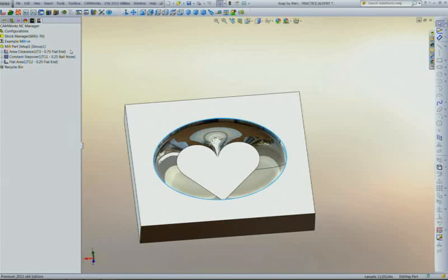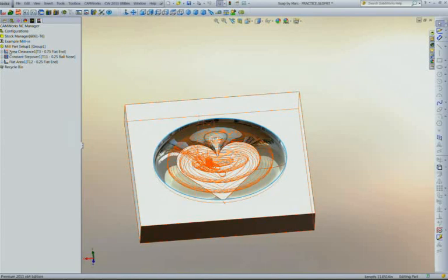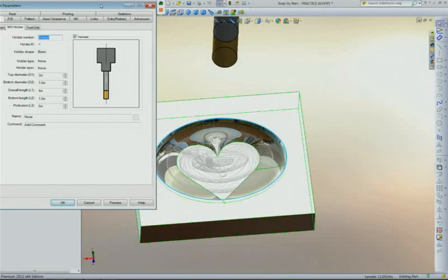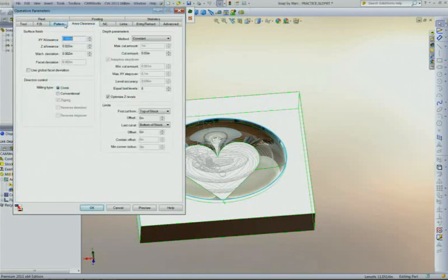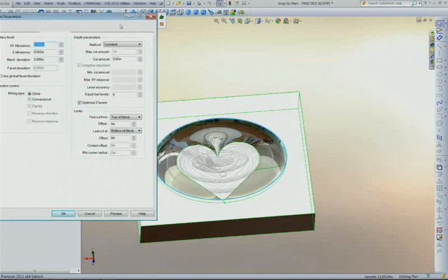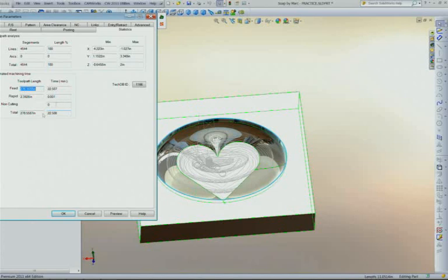Now I'd like to turn my attention to this particular roughing operation here. And I'd like to talk about another feature inside CAMWorks called Volume Mill. This is a new feature, and what Volume Mill can do is greatly reduce the programming time involved for machining this part. If I go to statistics right here, I can look at the time required to rough it in this particular operation, and that's about 22.5 minutes.